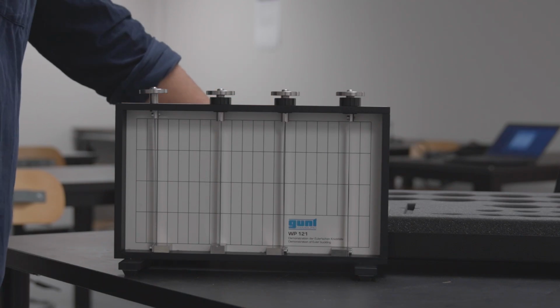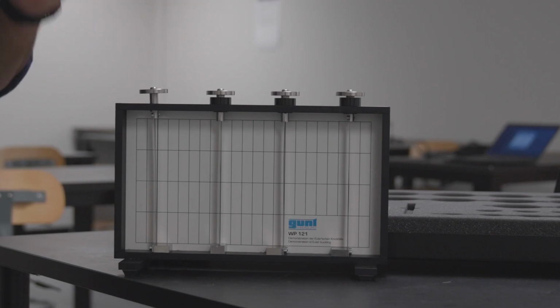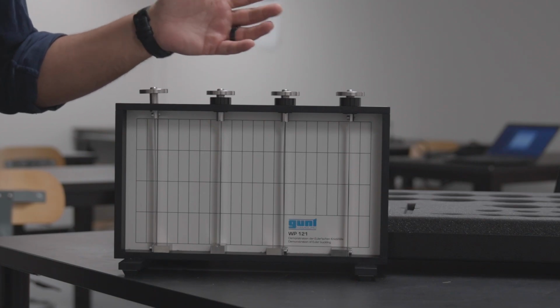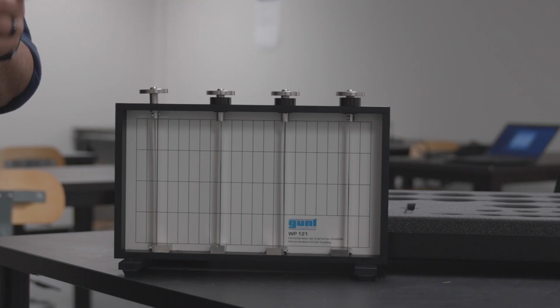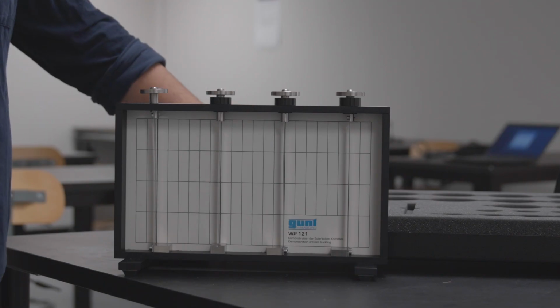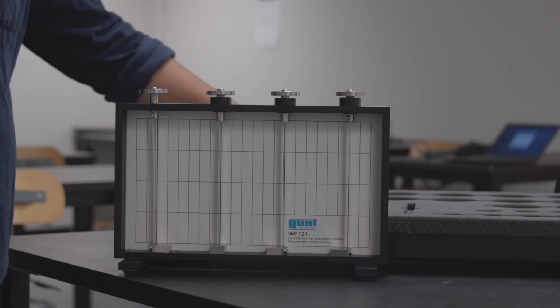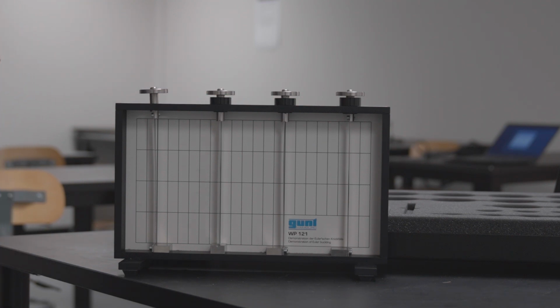All of these columns are the same material, so technically you are going to calculate the same modulus of elasticity. But because this is an experimental measurement, your modulus of elasticity might be different for each column. This is going to require you to do a statistical analysis and give us a confidence interval, 70% or 90%, based on whatever is in your lab memo.